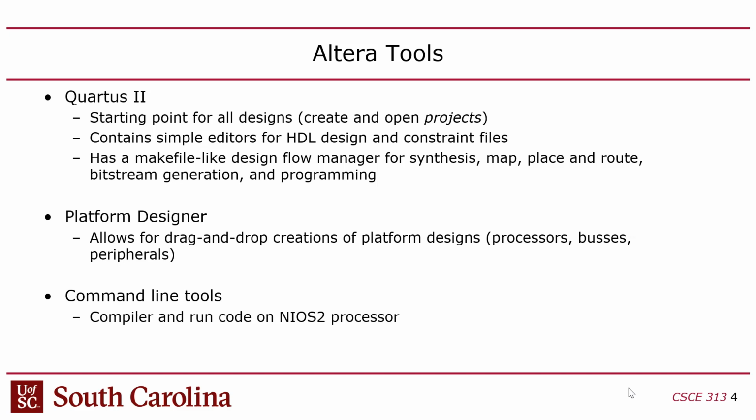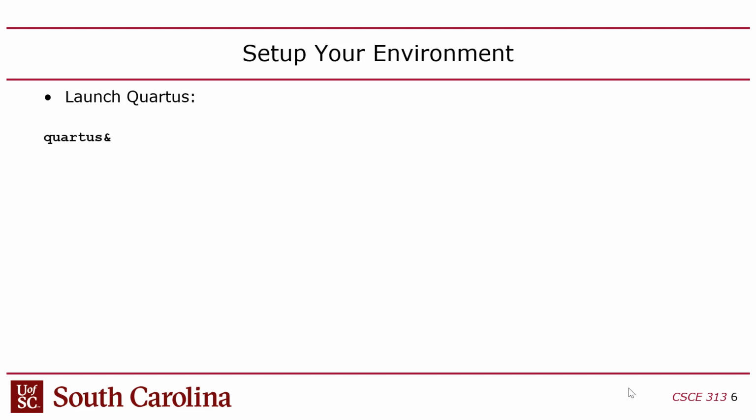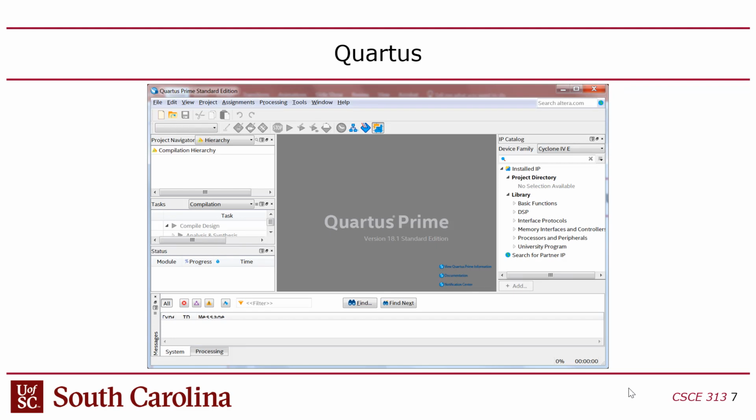Okay, anyway. All right, so let's see. So your environments: this slide says set up your environment, but it's blank. It just says run Quartus. The reason for that is because Ryan, the IT guy for the department, basically forces you, when you log in, inside the system bashrc file, to load the environment for you. So you don't have to worry about anything. You should be able to open up a window or terminal and launch Quartus.